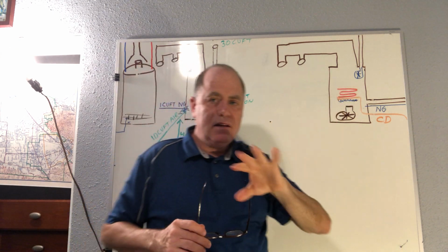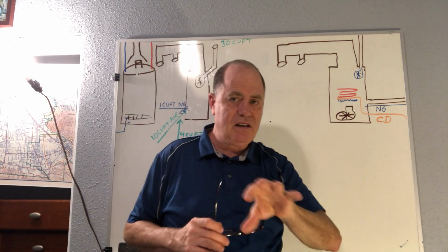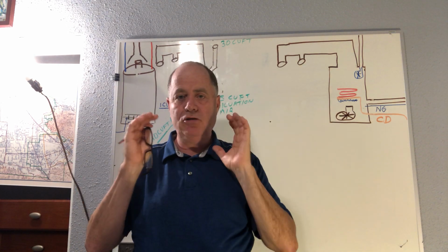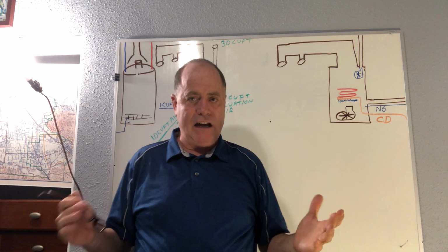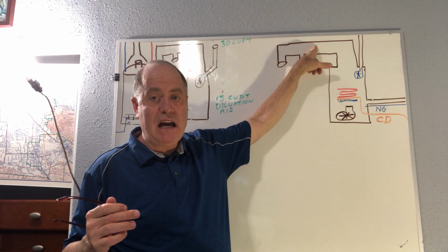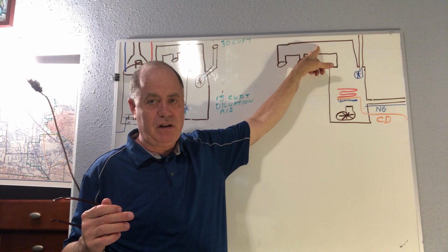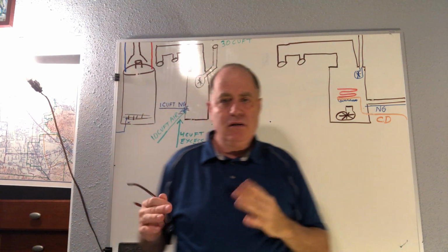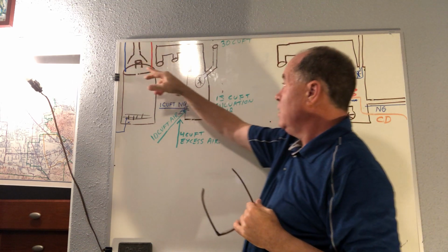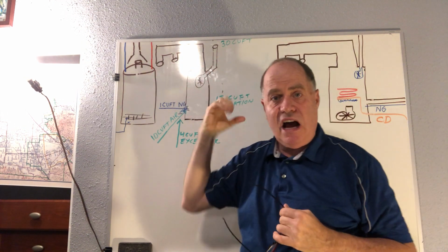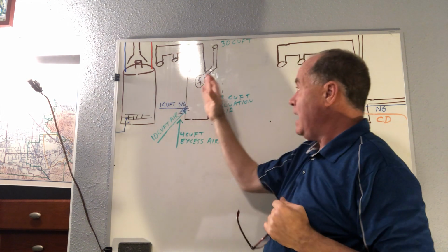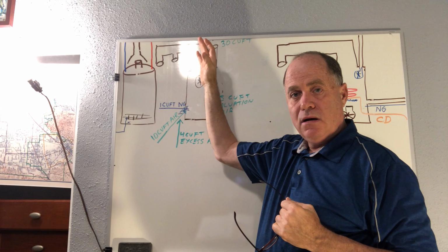But the reason that it's high efficiency is this: let's stick with a furnace where you're giving it 100,000 BTUs of perfect, nice quality natural gas. The amount of heat you get out of this is like 95,000 BTUs, 95% efficient. To explain that, if you were to touch this pipe or this pipe over here, it's hot, right? You're losing a lot of heat that you paid for out the chimney pipe, okay?